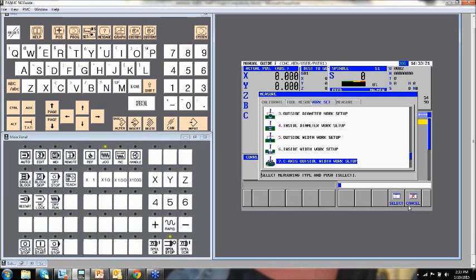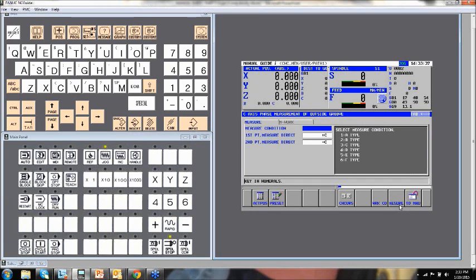And again, just to underscore, also within this, on the way I've got this control configured, because as I said, I'm using NC Guide, which is our offline software package that simulates a CNC control. But you can also do the C-axis outside. And with this, again, you get measure conditions, and then see it tells you to go to the plus C-axis side and the minus C-axis side.